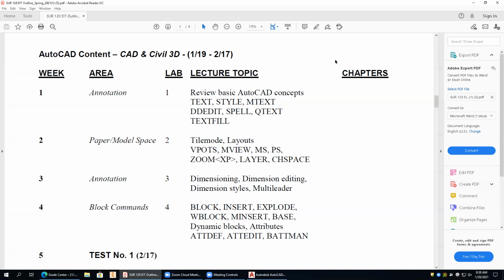So a style will drive how this text looks. This text is a different type of text. It's called multi-line text. That's what's in text. Now, it can be style driven or not, so it has more flexibility. Multi-line text is more like a word processor. You can do things like bold and italicize within the document, whereas with this type of text, you can't. So this is an older style type of text in AutoCAD. For simplistic labeling, though, this is a lot easier to use than this.